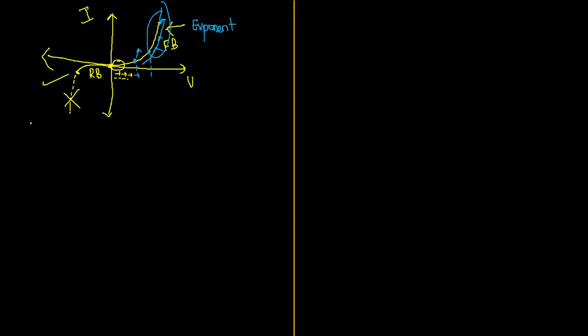Even in reverse bias you can observe the same pattern. Initially the reverse current will be 0, 0, 0. Then it slowly increases and gets saturated at the maximum point. If you push this diode to operate beyond this point, the diode will get damaged, because that is the maximum reverse blocking ability of the diode. It can block up to this level only. After that, it will automatically break down. Basically, reverse bias is called the blocking state.